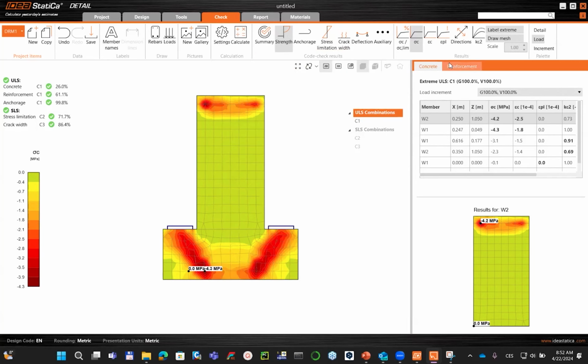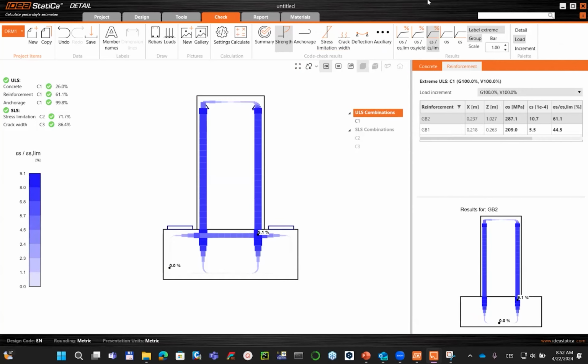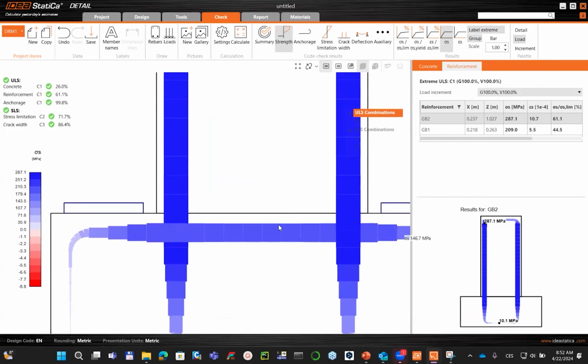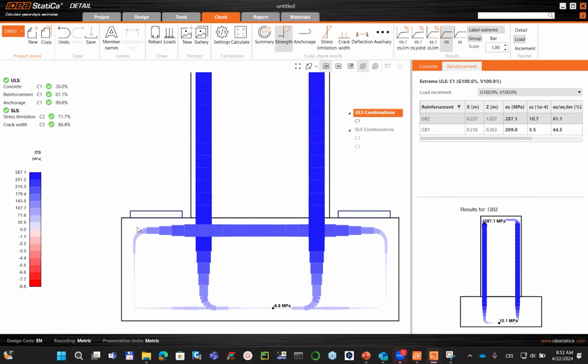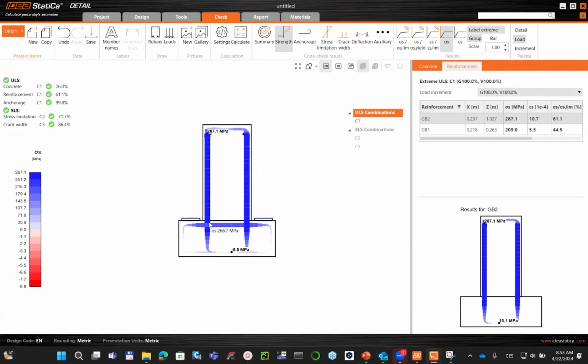What about the reinforcement? From the point of view of reinforcement, I would like to see what is happening on the structure. You can see the stirrups that are maximally utilized are the stirrups in wall number 2 in this web, because there is a big portion of the tension. Also, the horizontal rebars are utilized a lot. So this is how the structure is covering the tensile stresses.